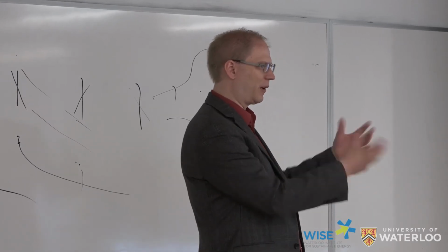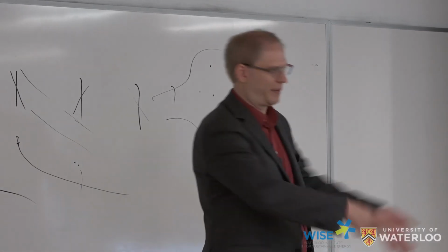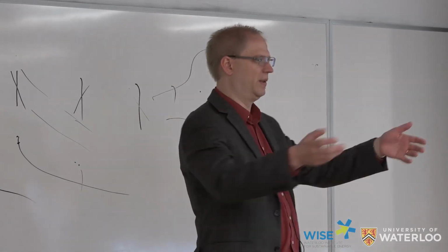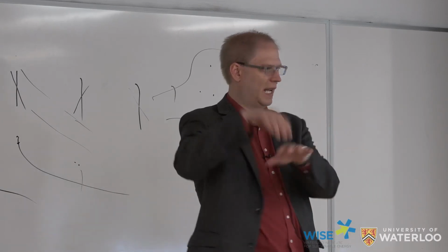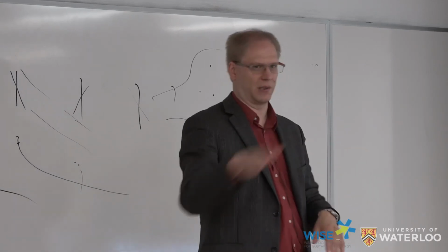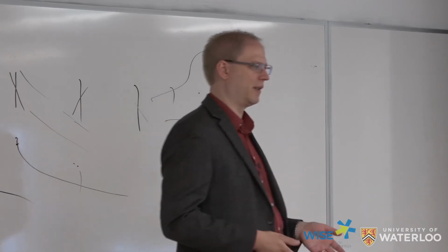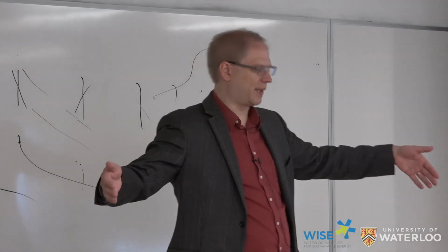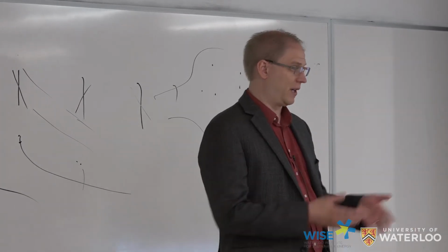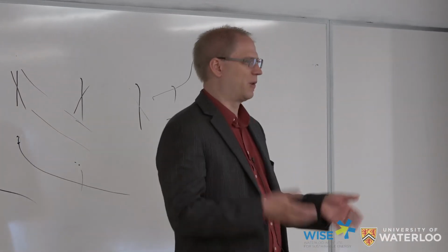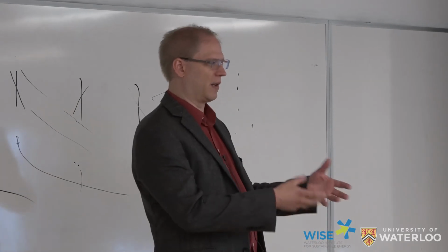What we've done is we've parameterized all the input. We ran about 50,000 FAST simulations. We fed it through. We said, well, based on the range of possible inputs, which ones of those are driving the outputs in the most sensitive way? Basically looking at the gradients and saying, what's the most sensitive? And so from my huge number of parameters, I can narrow it down to say, well, the top 5 are these, the top 10 are these. And if I know those, then I can do much more cool things with joint probabilities of those things.